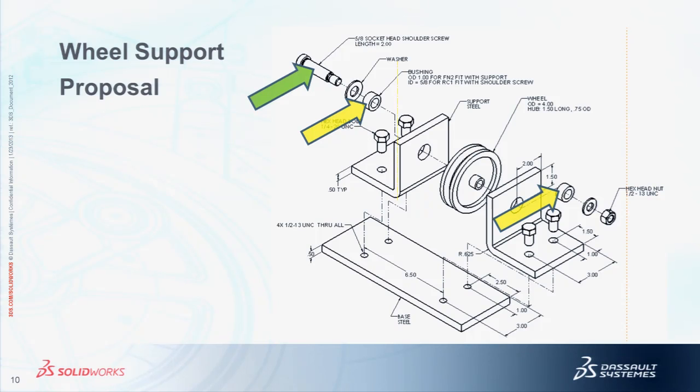I'm going to bore out the inside diameter of those bushings. I'm going to sock those things down to the plate. I've got clearance holes in the supports. So after I tighten this thing down, you're going to tell me that shoulder screw is going to slip right through there and everything's going to be fine.